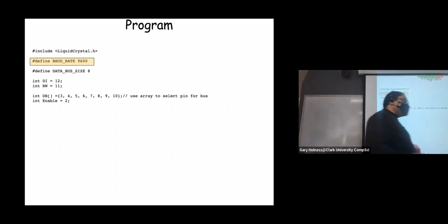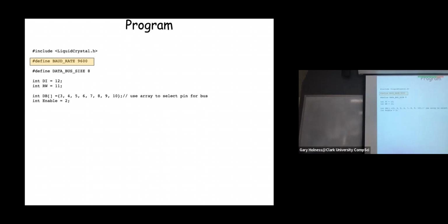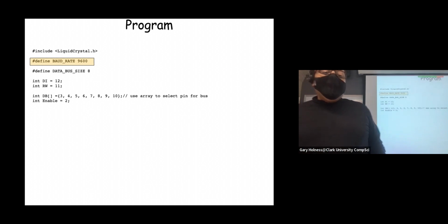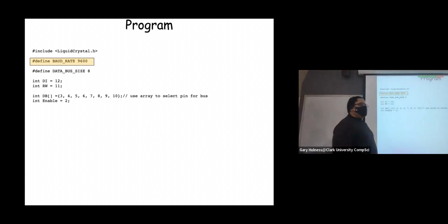Now recall, this microcontroller only has a really, really small amount of memory, relative to your desktop or laptop. And one of the things that takes up space in your program when you load it into memory are the symbols. Symbols are things like function names and variable names. And so my reason for using #defines is because after the preprocessor phase runs, this goes away.